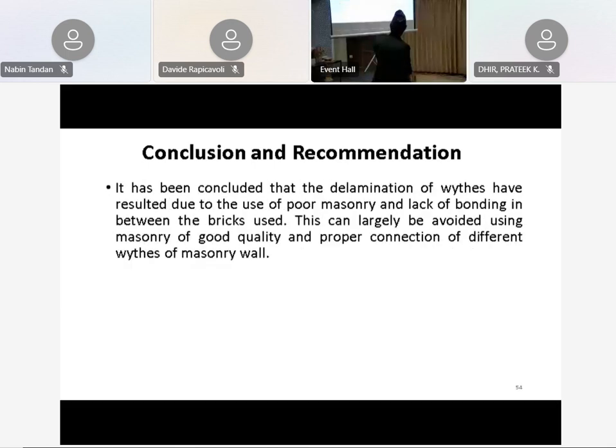Next. And we can see other things also. These masonry walls or buildings have a lot of age, almost 180 years, 100 years, and more. Because of it, these materials had already become weak, and they faced a number of earthquakes. Due to it, the bricks and mortars were shaken so many times, and we can see the micro cracks there.